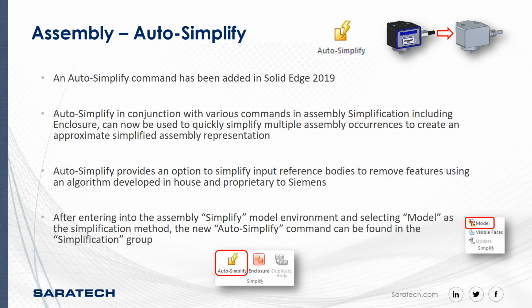Over the years, Solidedge has had a lot of Simplify tools, and this is just another enhancement to make it real simple and easy. It allows us to take multiple bodies and create a single body inside of Solidedge. We're going to be creating a simplified model. It'll take us into the modeling environment, where we have the new Simplify tool, or Auto Simplify.